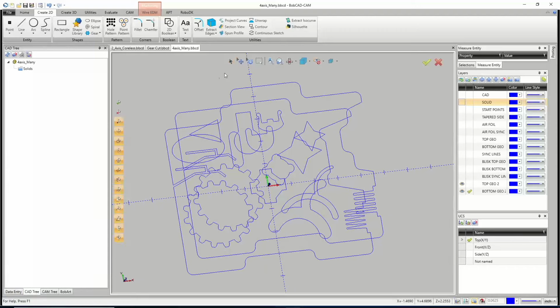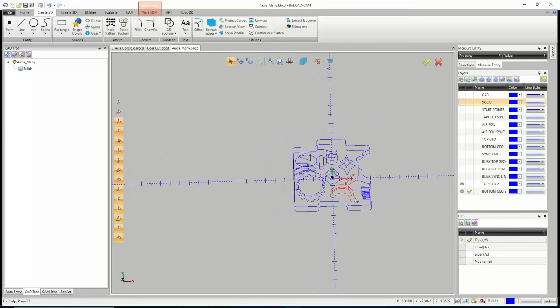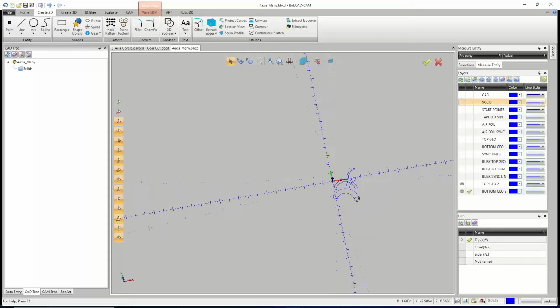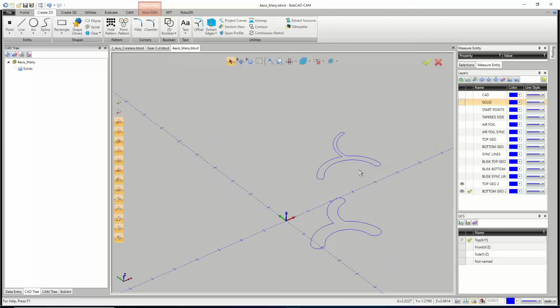We have a real quick, easy way of kind of cleaning that up. All I'm going to do is hold Shift and pick the 2 shapes that I want to work with. So they are the only 2 selected. Then I'm going to drag a box over everything else, including the 2 that I selected, and it'll deselect the 2 I had selected, and it'll reselect everything that wasn't selected. And then I'm just going to hit Delete. So there we are. Now we have those 2 little pieces of geometry kind of isolated.